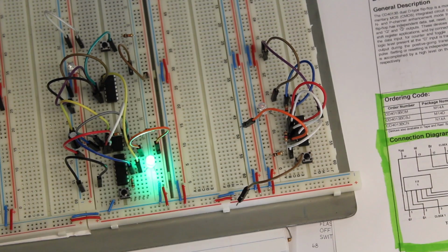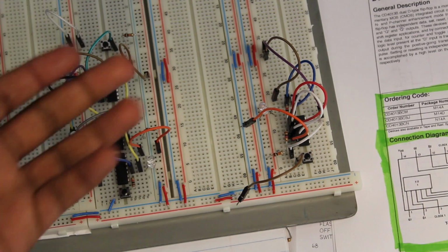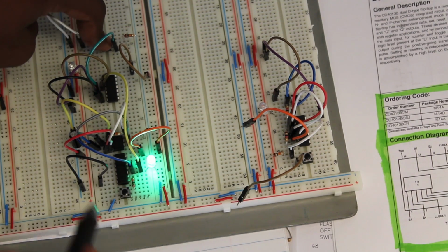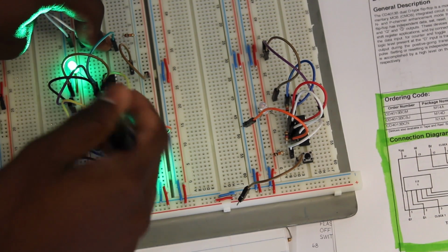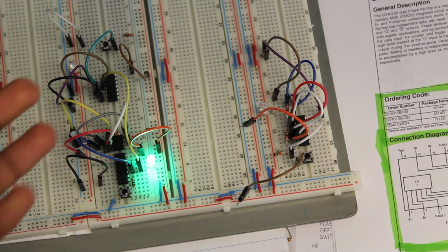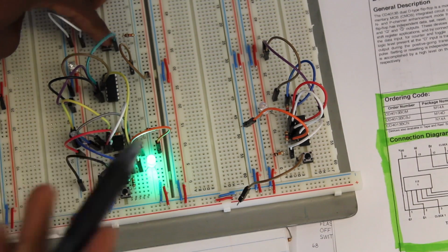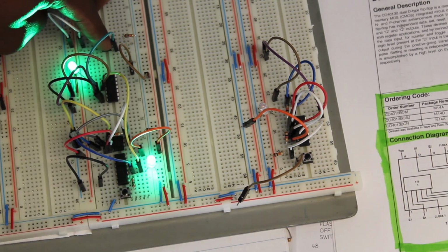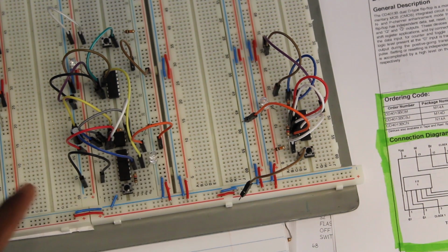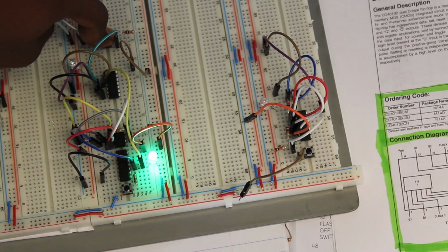Now, what you might think is that each clock cycle it's resetting the value, but actually that's not what it's doing. On each clock cycle, it's checking the value here. There's a terminal on this IC that is D, which stands for data, and it asks what's the value of data. When I press this, I make data high. So when this clock transitions from low to high, what is the value of data?